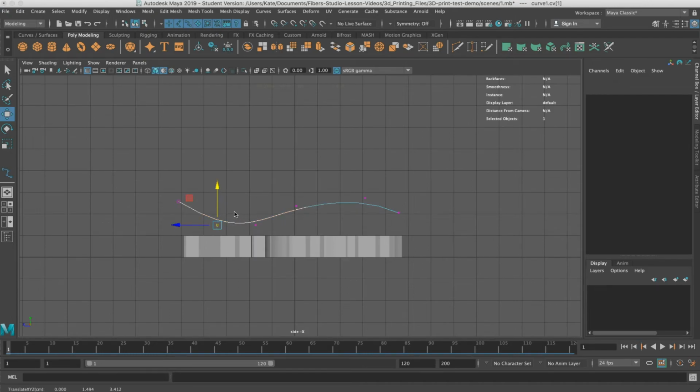If you click B, you have to select the vertex and then do B, and it will turn on. If you hold B and press with your left mouse button and move your mouse back and forth, you'll get this, basically a brush setting. What it does is it moves it more organically. So if you want to make small adjustments, it's a good tool to use.